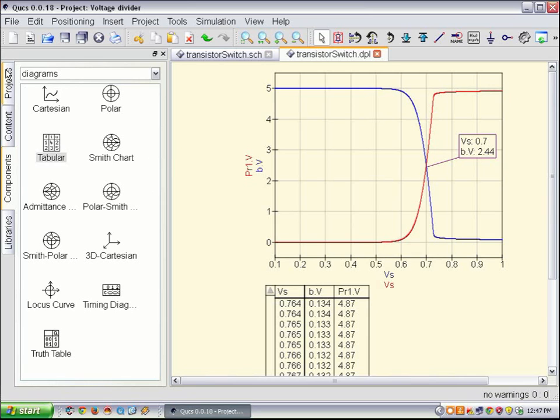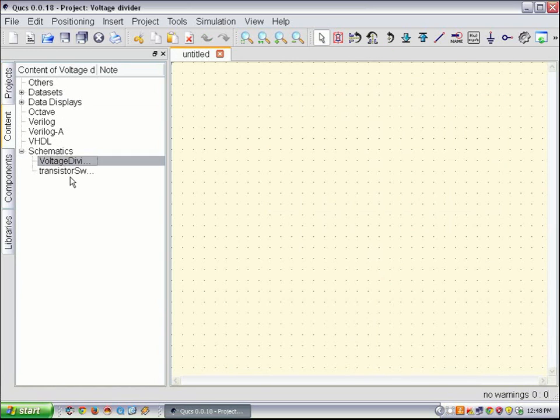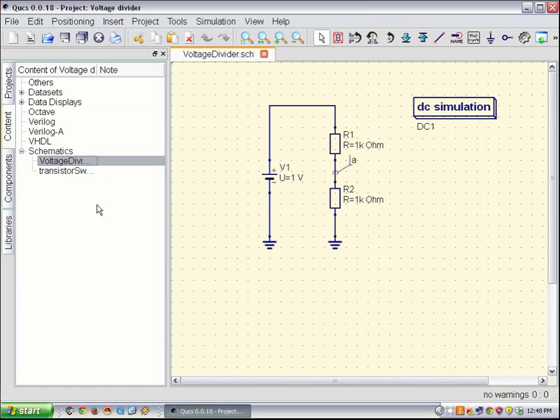So now we go back to our voltage. So we are going to use this kind of a switch in our voltage divider circuit. So I will save all and then go back to voltage divider. So I have got two circuits in this. So I will select voltage divider circuit. Now in this I am going to add a voltage divider. So it means I must set the value of this R2 or this R1 so that it is 1 volt when there is going to be a source. So it must give me 0.8 volts.